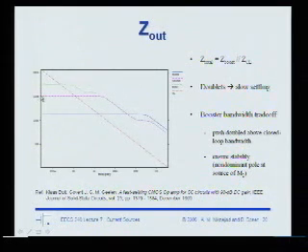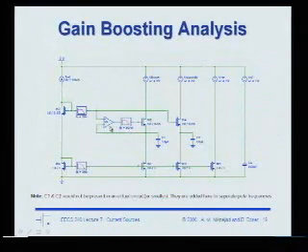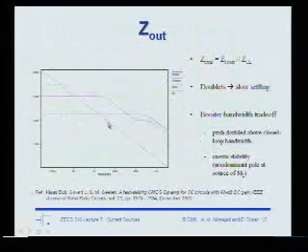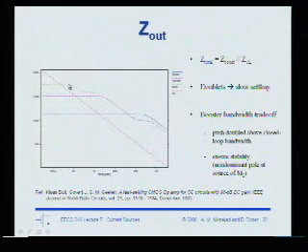And then finally, the boosted amplifier is this top curve. You can see here the gain is 10, so we expect the boosting to be a factor of 10, and that looks about right. So here's a gain of 10, and then right around 10 Hertz, you can see that the boost goes away, right? So you only get the boosting within the bandwidth of the amplifier.